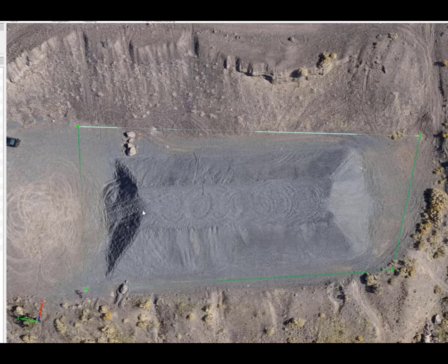So as you can see, it's a futile attempt to keep the ATVs at bay. They've been putting in large boulders. Our thinking is, could you just put a boulder at the 4 corners of the gravel piles, set a PK nail, paint a pre-mark on it, then record the distance between the pre-marks, fly an automated drone flight, process the data, just measuring the pre-marks and putting in a distance. Could you get an accurate volume?